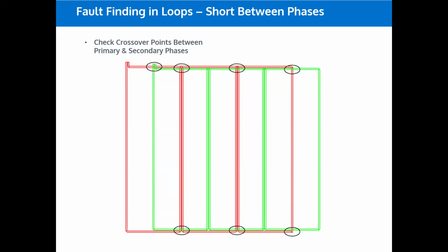Just make a point of lifting the copper tape here and putting additional insulation underneath, and by doing that with all these different points, one of them will be causing the problem. You don't know which one it will be, but do one each in turn, test it until you find the one that's causing the problem, and then that's it fixed.